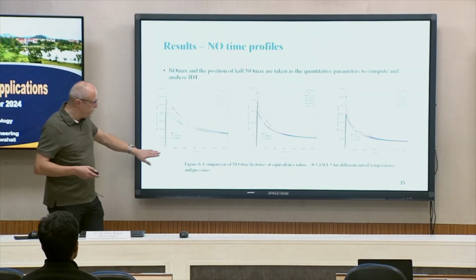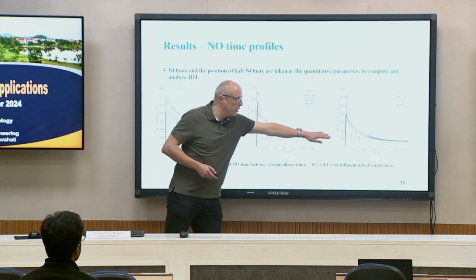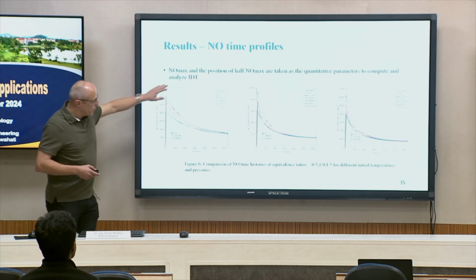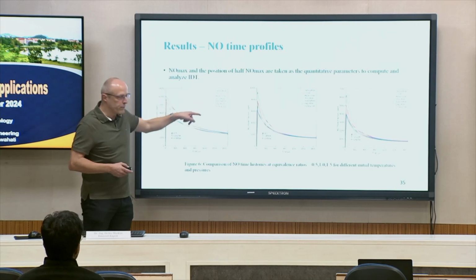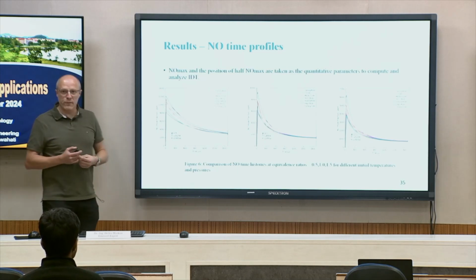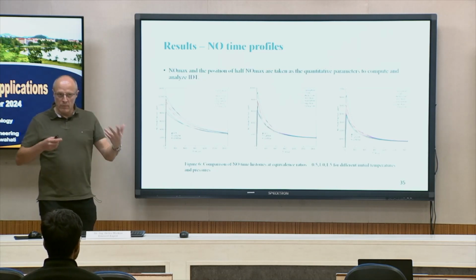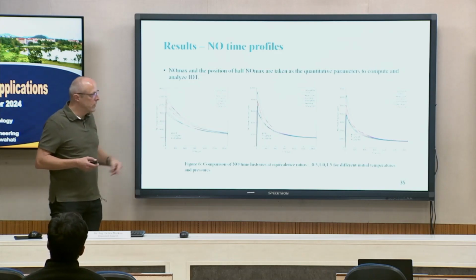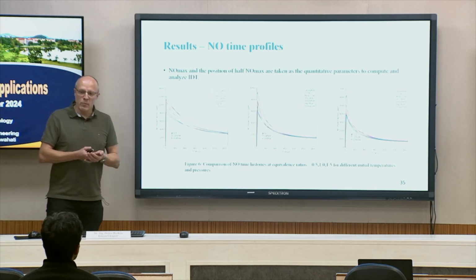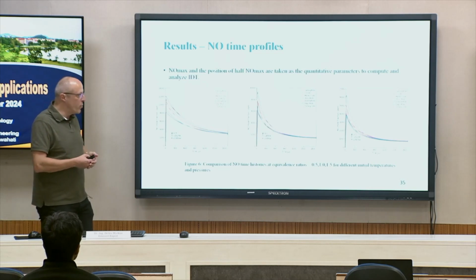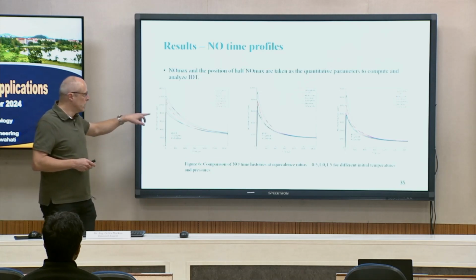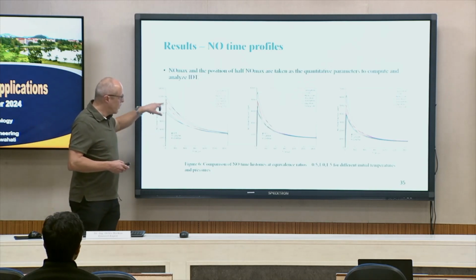So it's phi equals 0.5, 1 and 1.5, and here you can see for all the different models we have used the NO mole fraction as a function of time. And you see, of course, just in one picture, a lot of discrepancies. So each reaction mechanism is maybe perfect for a specific condition, but is maybe not the best one for our specific condition. So you see large discrepancies here, NO as a function of time.